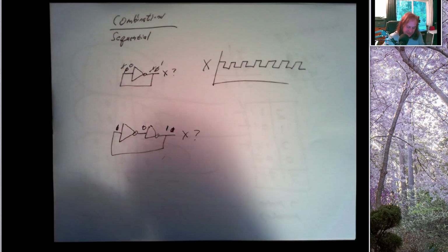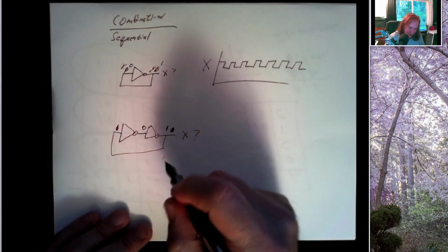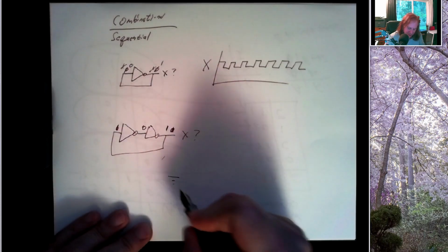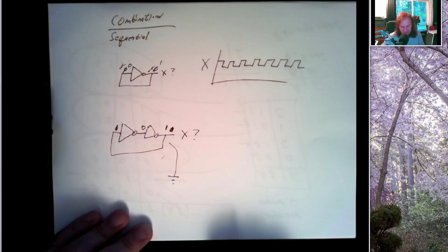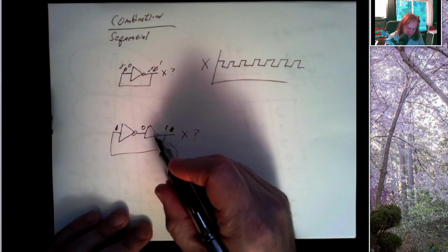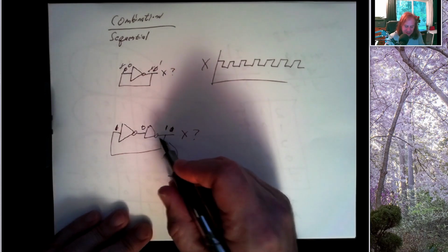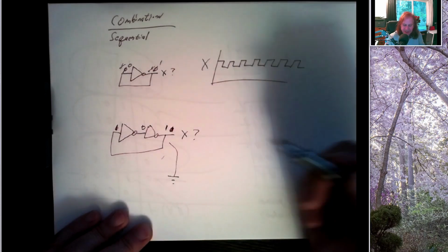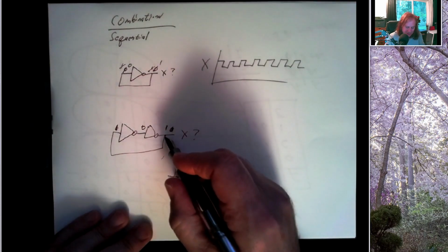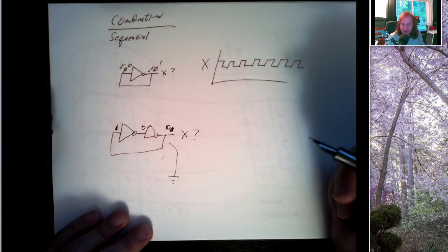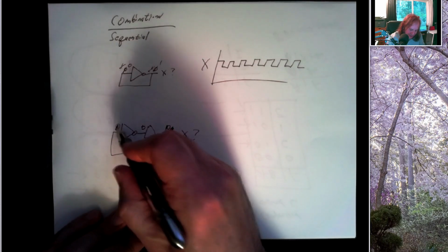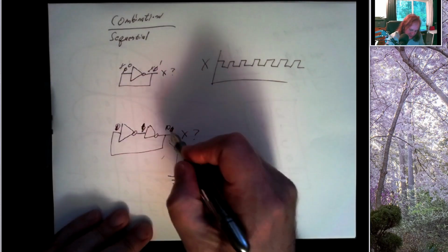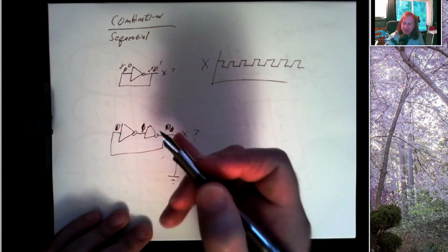But if I were to take a wire connected to ground and just momentarily touch it right here, even though this chip is trying to put out 5 volts, just tap a wire here that's connected to ground. That will pull this output down to 0. And then when I take that wire away, that 0 goes in here, gets inverted to a 1, gets inverted to a 0. This X is going to remain a 0.